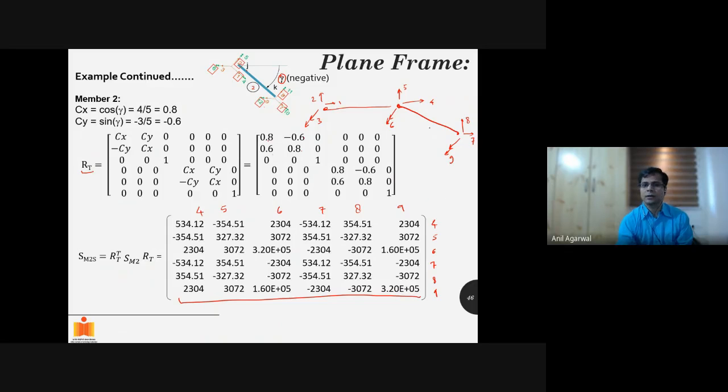The stiffness matrix that you had earlier belonged to this, and then this rotation. Likewise this, and then this rotation. That was the original stiffness matrix. In that original stiffness matrix, you may remember the axial behavior and the flexural behavior. I'm still calling it 4, 5, 6. Actually the degrees of freedom were different, but I'm calling it that to keep a similarity between 4, 5, 6 here and here. You may remember that the terms belonging to 4 had no non-zero relationship with the terms belonging to the 5 and 6 degrees of freedom, right? That's why you had zeros here and zeros here. Remember that? But now you don't have those zeros here.